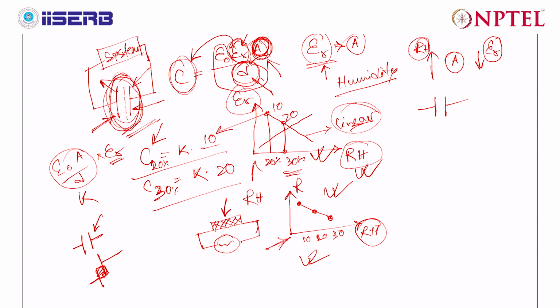So these different aspects will help you in designing different sensors, and in thinking about whether to go ahead with a specific structure for a humidity sensor or not. For example, for a humidity sensor, the material present as a dielectric in between the two electrodes should come in contact with the ambient condition.